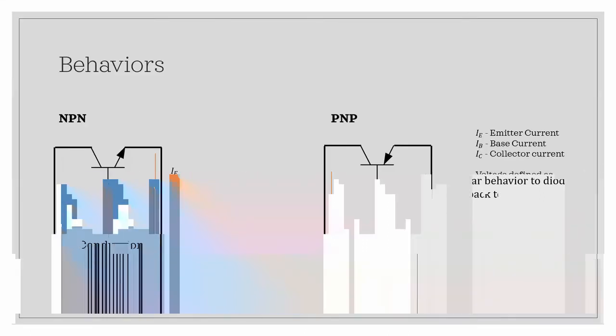First, we're going to look just at transistors hooked up to some power supplies. For convenience, no matter the type of transistor, the lead with the arrow on it is always called the emitter. The central lead is the base, and the remaining lead is the collector. This naming convention applies to voltages and currents as well. So if you wanted to know the voltage going into the transistor across the collector, you would just call it the collector voltage, and so on.